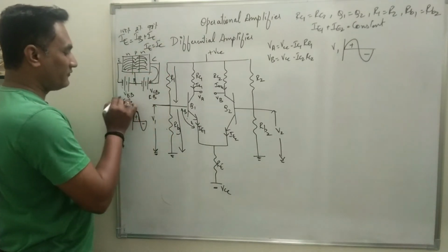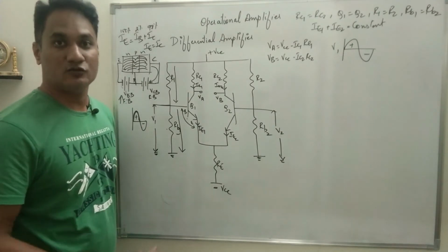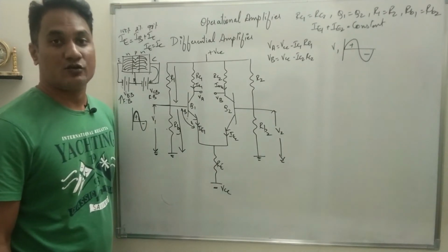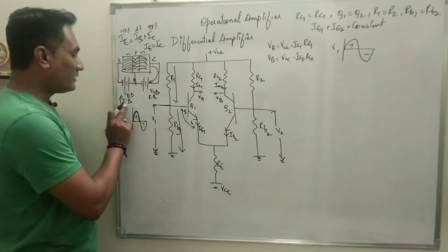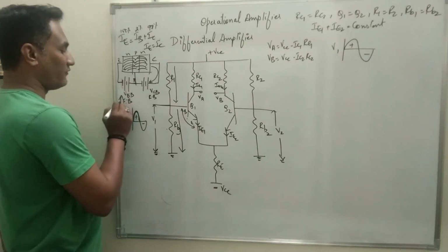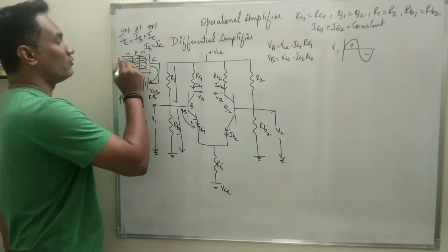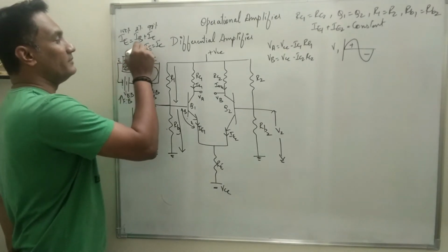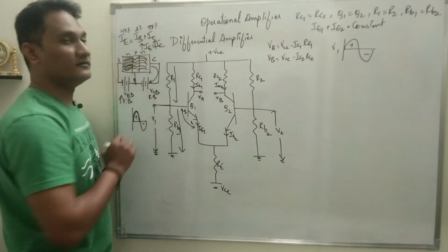Now what happens if the forward bias voltage is increased? I have explained this when we tried to understand the transistorized voltage regulator in chapter 2. If the forward bias voltage increases, more charge carriers will move out of the emitter into the base, that means emitter current will increase, and as IE is equal to IC, IC will increase.